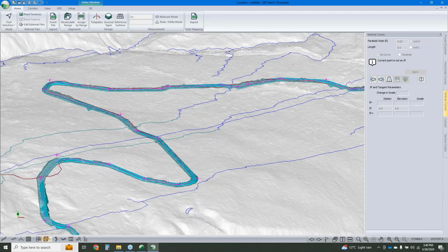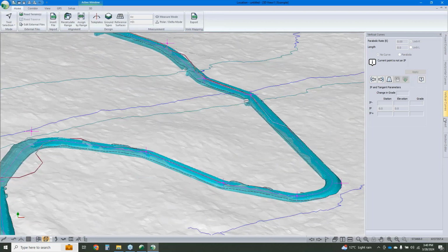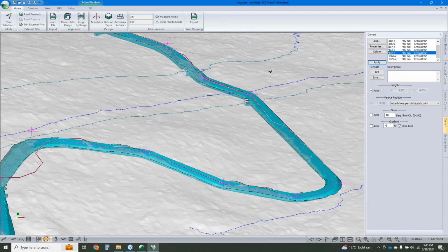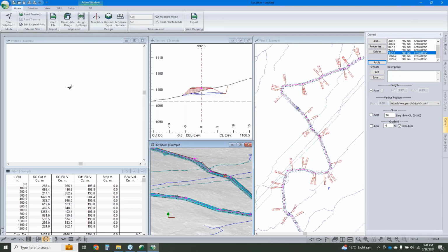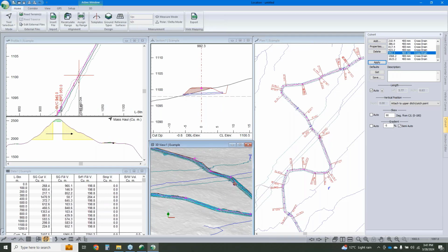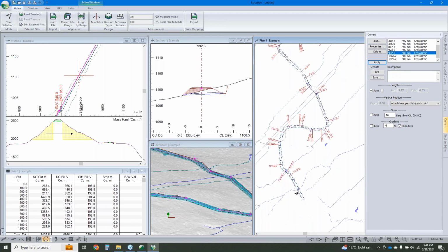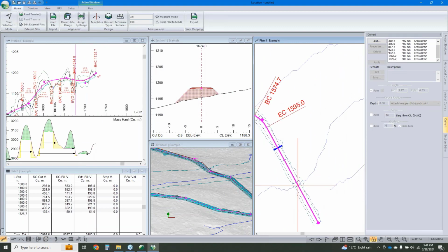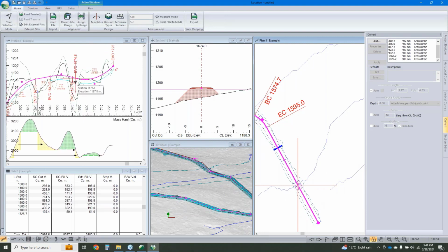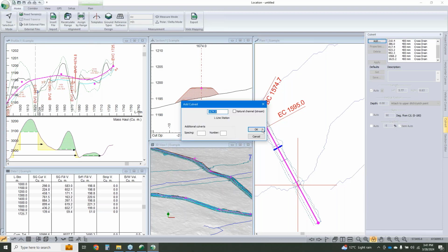And we can see I've got various locations where I've already added in culverts. So here I've got a pipe about there. We can see our cross section where that's at. We can see it in our profile. And I'll add in one extra pipe here at the end. So I've got a bunch for this to be interesting when we do our analysis, but I'll add in one and it's kind of all the same beyond that. So I'm in my culvert panel. I'll click add.